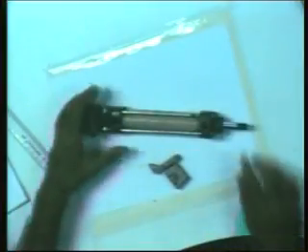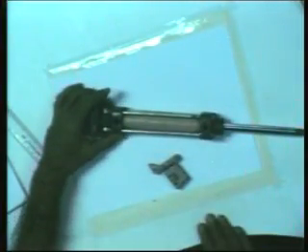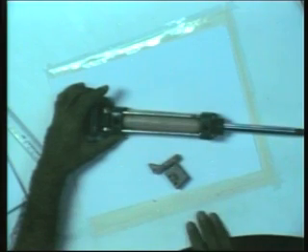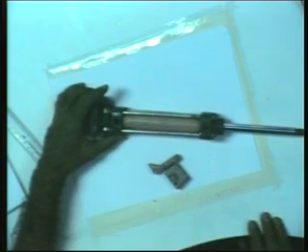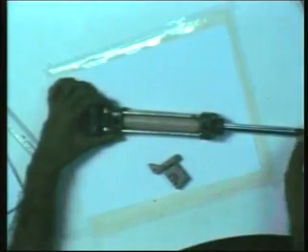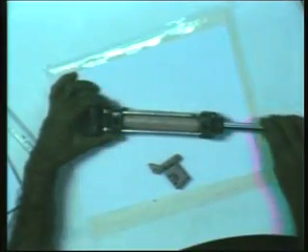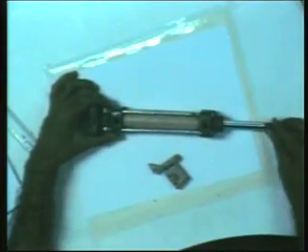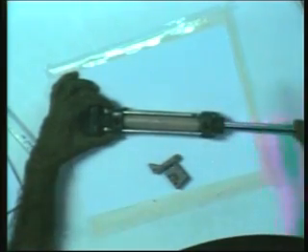A pneumatic device: once you admit air, let's say the piston is here, it shoots to the other end. It goes with a solid jerk to the other end. And when you admit air here, it goes back to the other end. These pneumatic actuators typically cannot be stopped in between. You can't stop it here. You are either here or you are here.